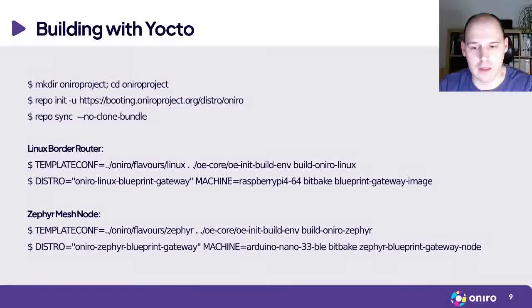On the Zephyr side, you can also use bitbake with the flash command to actually flash the firmware image onto the device. It's all wrapped nicely in bitbake, so you don't have to go around and look up how to flash the device, for example.